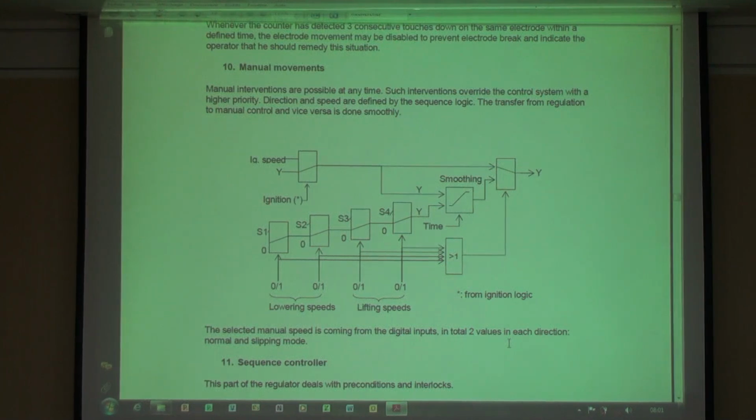Every client, most of the time, the furnace has installed diesel and accumulator, because the accumulators are necessary anyway to smoothen the movements, and because sometimes the pump cannot deliver the flow rate, especially when you want to lift up the electrodes and lift up the roof together. So there is no way you would install a big pump for nothing. So it's better to install accumulators.